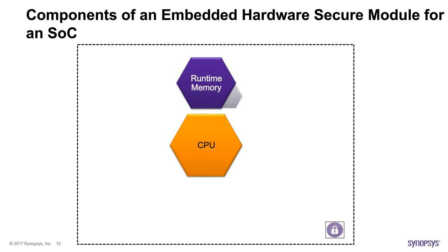Tamper resistance is the next one. It's an essential feature for this product. So code from the outside needs to be validated prior to running it on the secure CPU. This can be implemented in many ways, including a dedicated ROM that can only be accessed by the hardware secure module. Now, this implementation doesn't scale very well, but it does ensure the integrity of the code.